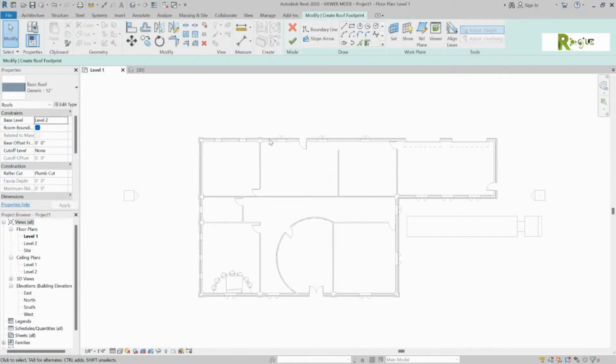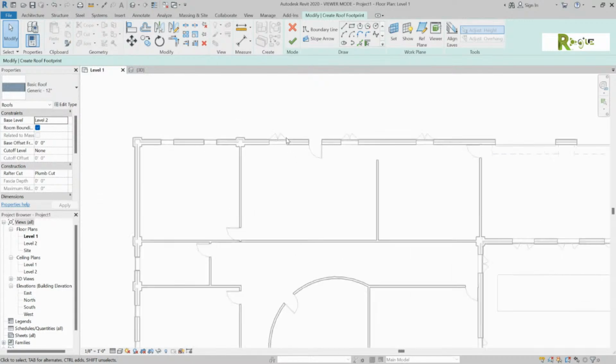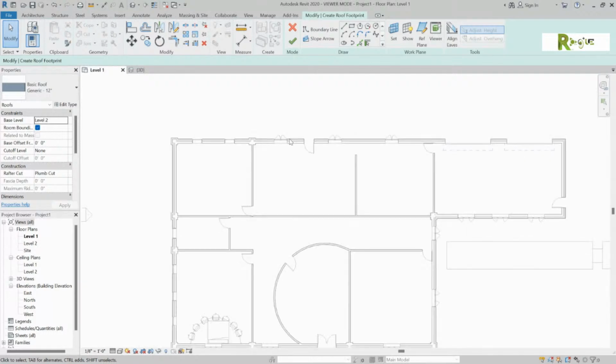Listen, did you get to watch Ginger drawing the family the other day? Because you're in what's called sketch mode. We know that when there's a red X and a green check box, you cannot place windows. You cannot do anything else until you get rid of that green checkbox or that red X, either one. Now, typically, you'd want to just start over. But what I want to show you is all you need to do is, when you pick the roof, it went into the boundary line command. So hit the little boundary line next to the red X.